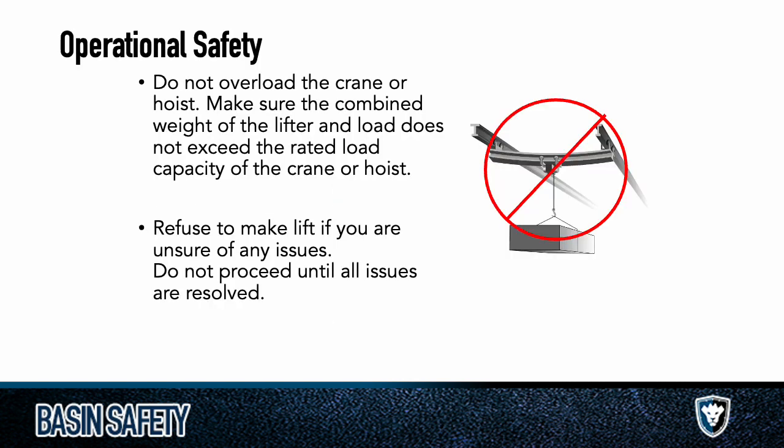So do not overload the crane or hoist. Make sure the combined weight of the lifter and load does not exceed the rated load. And again, I'm a big fan. Now it's more difficult with overhead cranes, right? It's not like, oh, let's get a heavier crane in here, right? It's installed. It's there. So I do recognize it's easier said than done, but that's my recommendation: make sure you're well below the lifting capacity or the weight capacity of the actual crane.